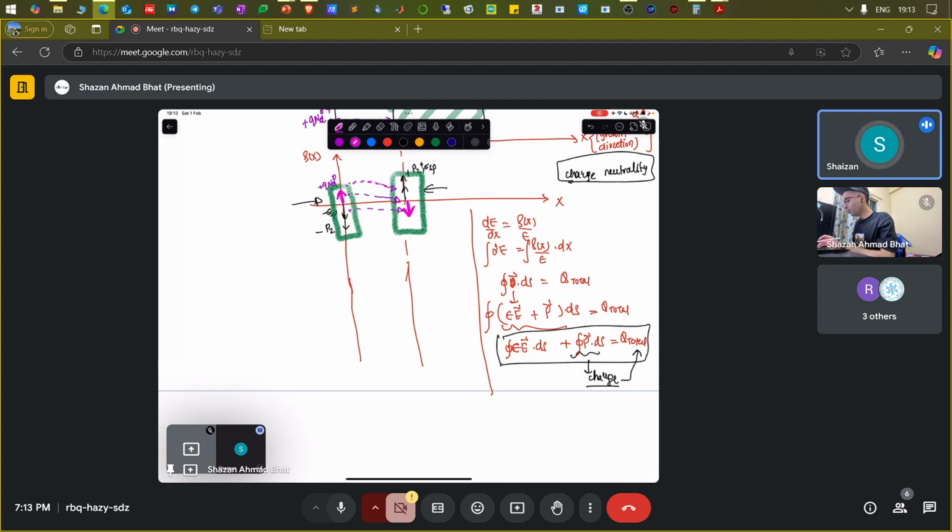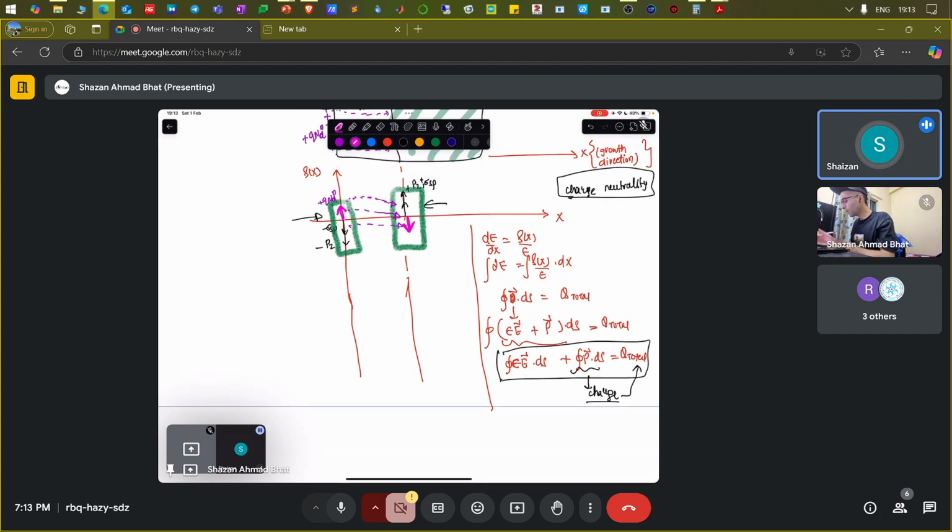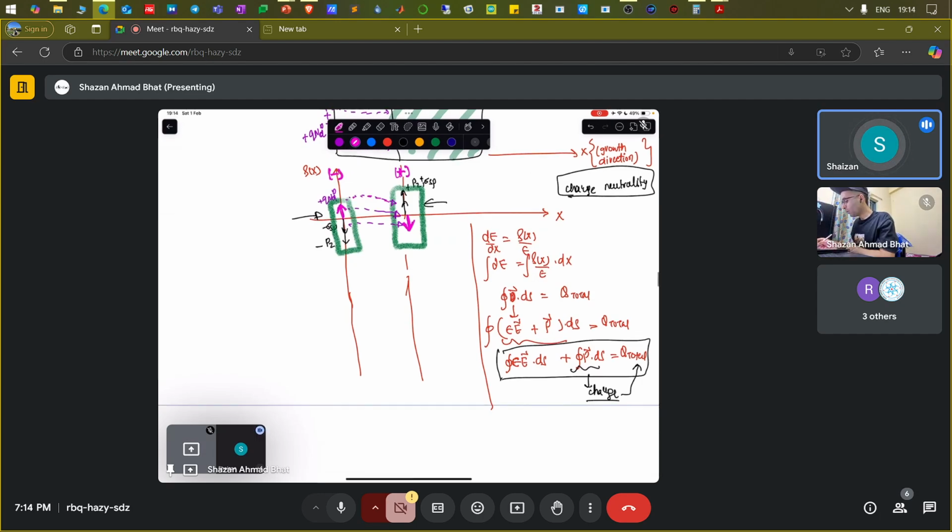Okay. But now when you consider the overall charge, you see that this is overall positive because of the huge piezoelectric and spontaneous polarization components, and this is overall negative again because of these polarization components. The donor charges are very small, yet they give rise to a very large number of electrons, which we will see in the upcoming slides. So now you have an overall positive charge here and an overall negative charge here. This is a very simplistic picture.